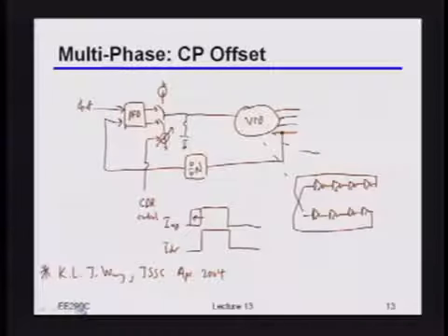So what's kind of painful about doing that in this particular design? Why does that kind of suck if you want to have the thing wrap? It's analog. It is analog, but let's be more specific. What would you have to do when the thing wrapped? Take your current from high to low? Yeah, exactly. What you'd have to do is figure out the magic current level such that, if I flipped it back from the high level to the low level, it gives you exactly 360 degrees of phase shift.